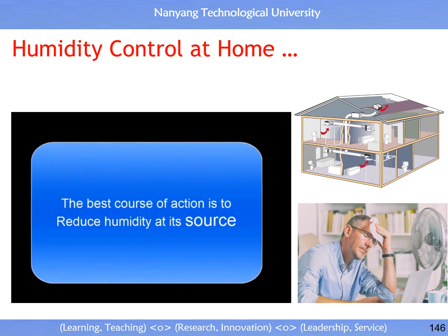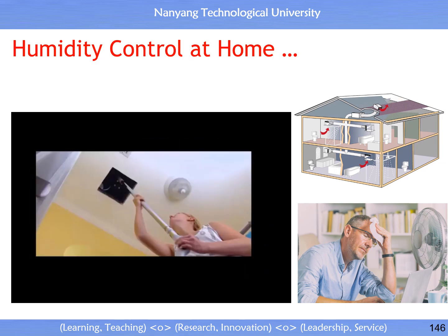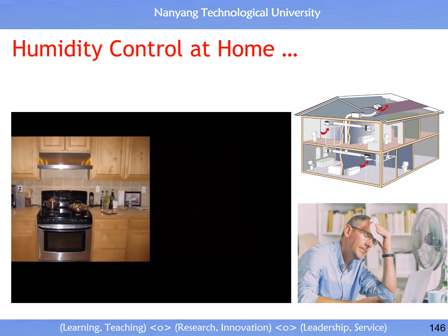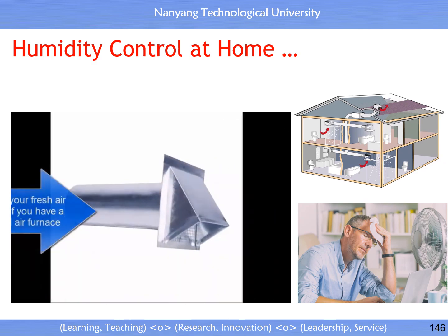When tackling indoor humidity, always improve the areas where the moisture is being generated. Installing good quality bathroom fans and cleaning the unit seasonally will help keep the exhaust fans effective. Cooking range and other exhaust fans should be directly vented to the exterior and not into the roof perimeter soffit.